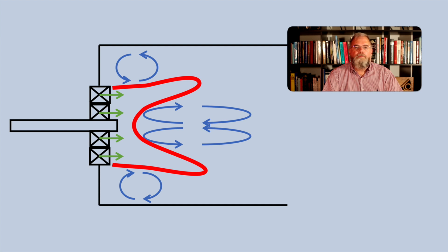At full load, both fuel stages are fed fuel, and the flame and aerodynamics of the combustor is very similar to the non-staged burner. Fuel from the inner swirler feeds the flame, which is stabilized by the recirculation zone at the center of the combustor, which is produced by the breakdown of the vortex, while fuel from the outer swirler feeds the flame, which is stabilized by the outer recirculation zone, produced by the sudden expansion of the flow.